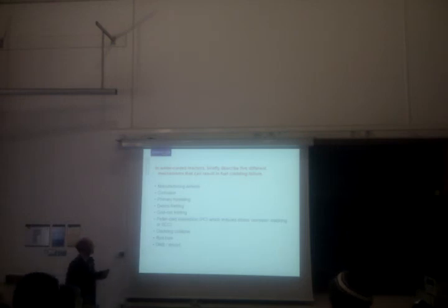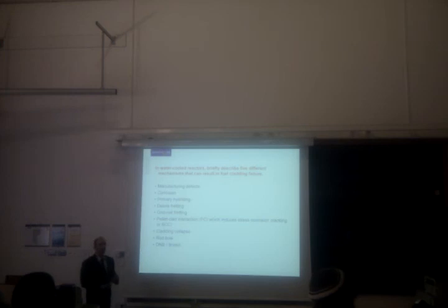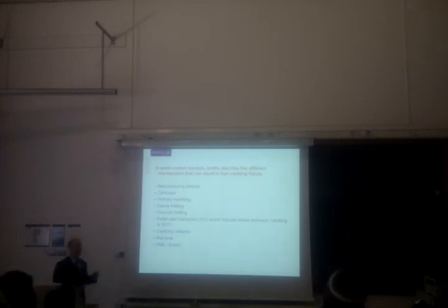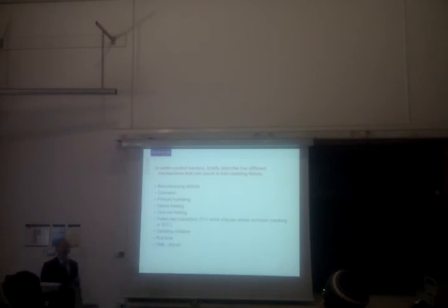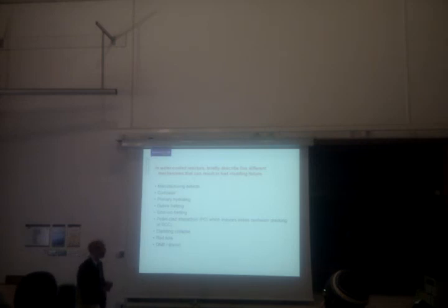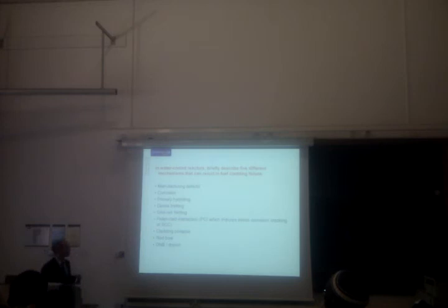Rod bow is simply the effect that we get when we fail to remember that zirconium alloys grow due to irradiation. Pretty much the same way that graphite does. It's a very similar crystalline structure. It's a close hexagonal structure, and you tend to get shrinkage in one direction and growth in another.